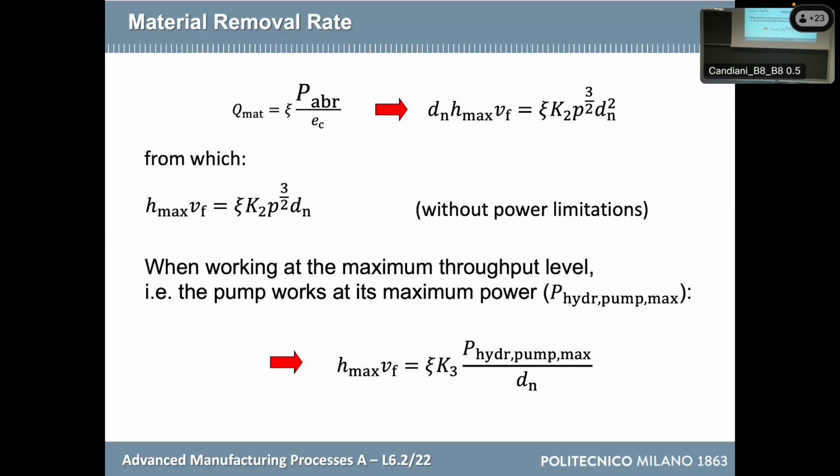And then we have two cutting performances, because we have the depth of the cut and the feed rate. In other words, we can use the power that we have at our disposal, that is represented in the second member, and we can use it for cutting into the depth or for cutting fast. And this is absolutely